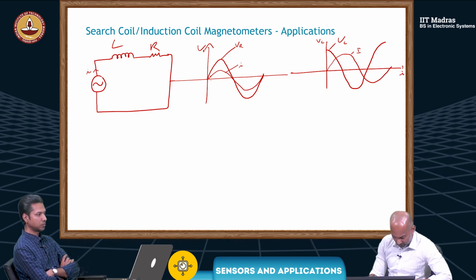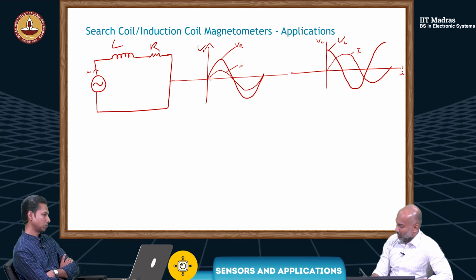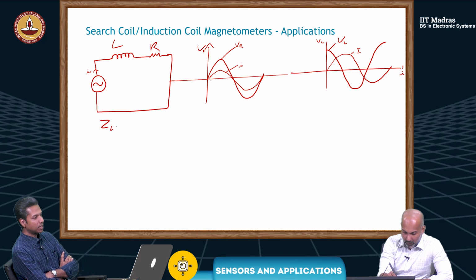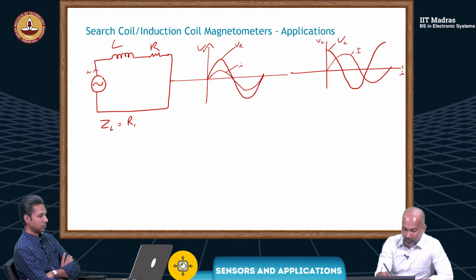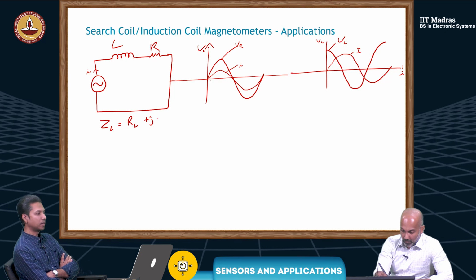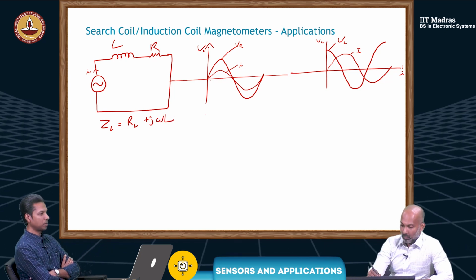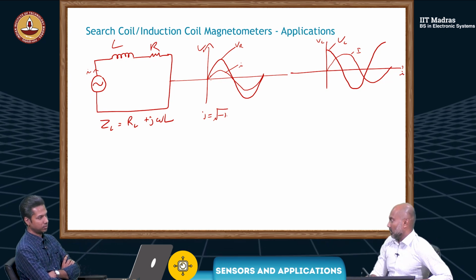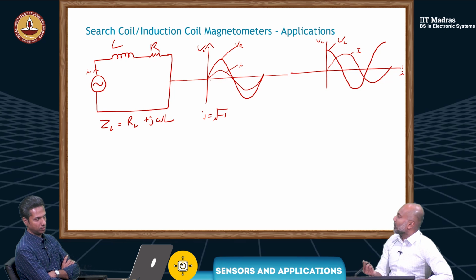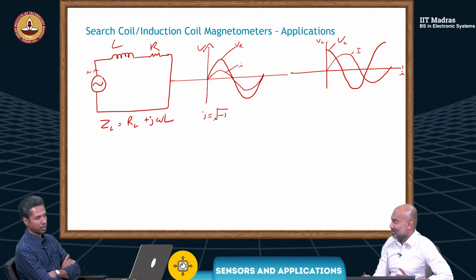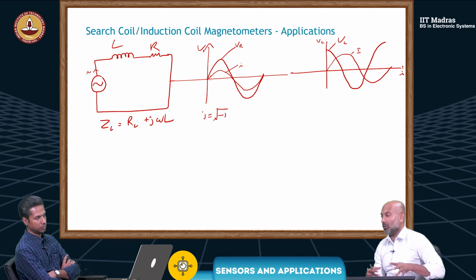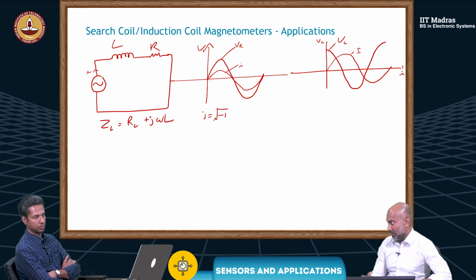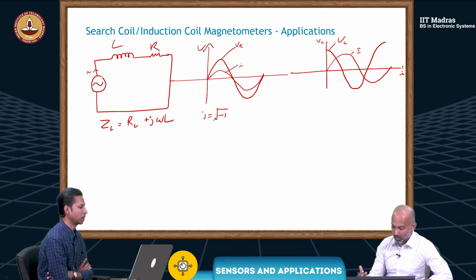Can we use this phase difference somehow? So again, it will tell us whether it's more resistive or more inductive. That we will come to know. Even with the pure impedance, we can do that, right? But if you want to know if it's the permeability or the conductivity, then it's a little bit harder to do. That doesn't give you that information. Correct.